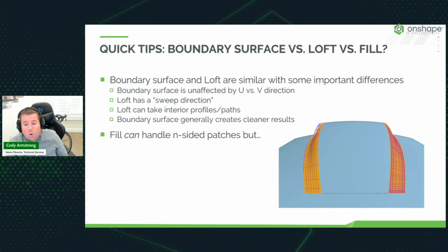Now, the question that commonly gets brought up, and I want to take a moment to address this, is, well, when should I use boundary surface? When should I use loft? And when should I use fill? Well, I think the simple answer to that is if you can use boundary surface, you will probably end up with the cleanest surface, right?